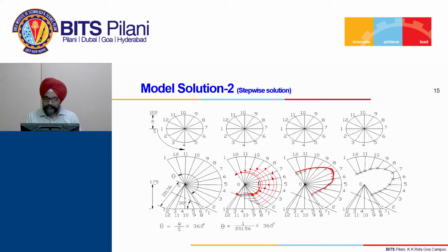And finally, if you cut this particular shape on sheet metal and give it a turn, so that the last and the first end meet together, that will give you the shape as desired, the shape which is in the front view, which will look like this one. Okay. So, it is like the frustum of the cone, because the upper part of the cone has been removed. So, this way you can transfer the points on the cone.